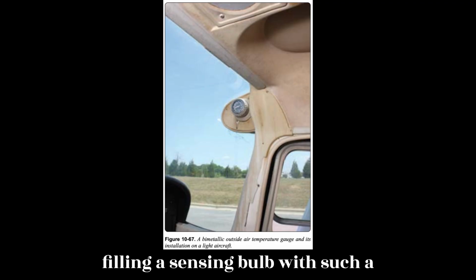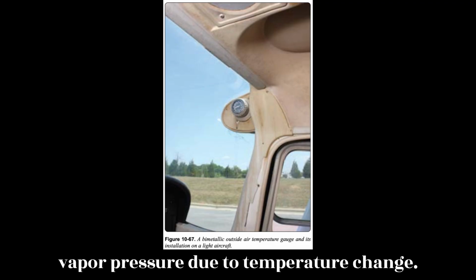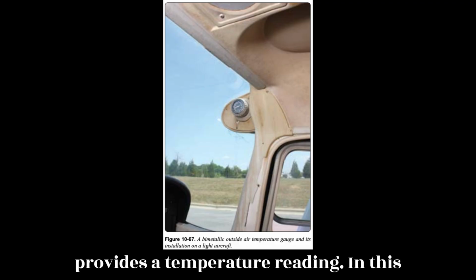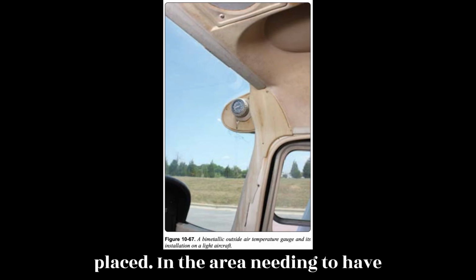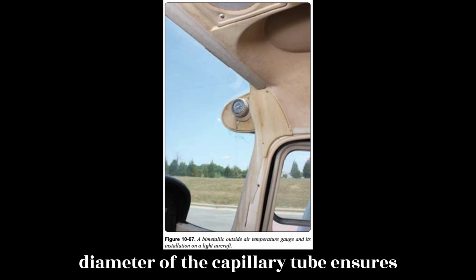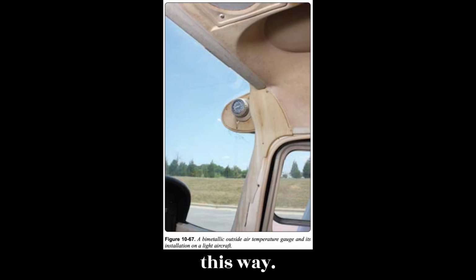By filling a sensing bulb with such a volatile liquid and connecting it to a Bourdon tube, the tube causes an indication of the rising and falling vapor pressure due to temperature change. Calibration of the dial face in degrees Fahrenheit or Celsius, rather than psi, provides a temperature reading. In this type of gauge, the sensing bulb is placed in the area needing to have temperature measured. A long capillary tube connects the bulb to the Bourdon tube in the instrument housing. The narrow diameter of the capillary tube ensures that the volatile liquid is lightweight and stays primarily in the sensor bulb. Oil temperature is sometimes measured this way.